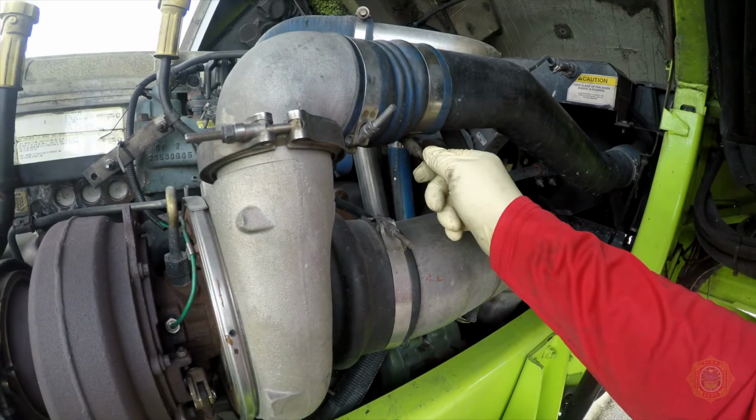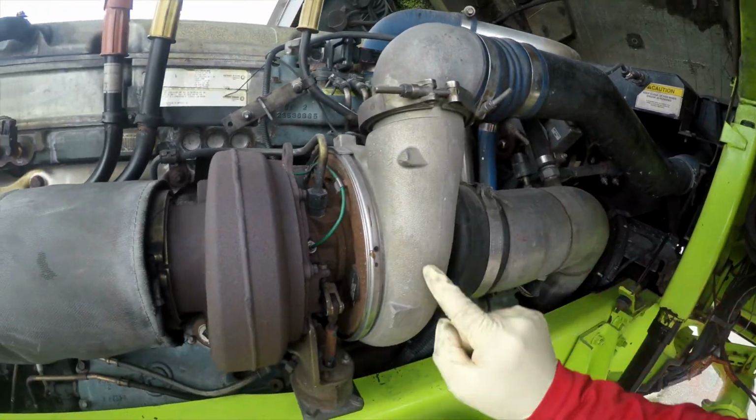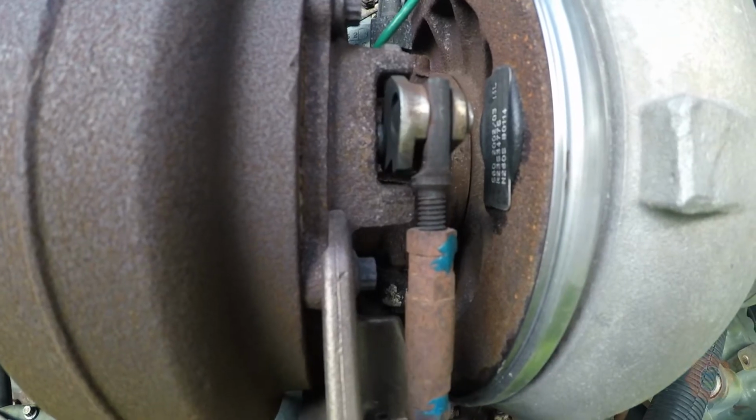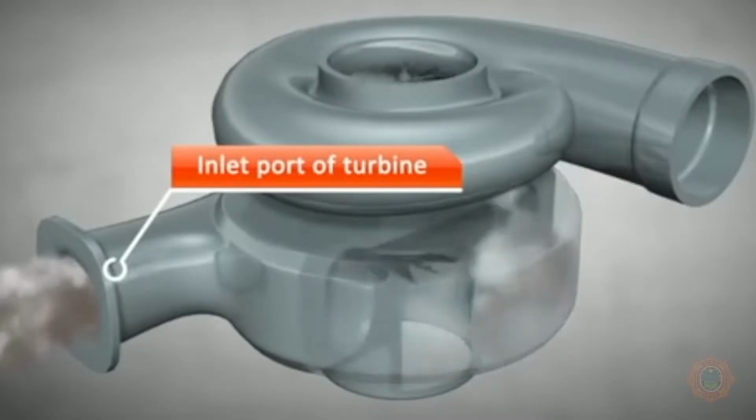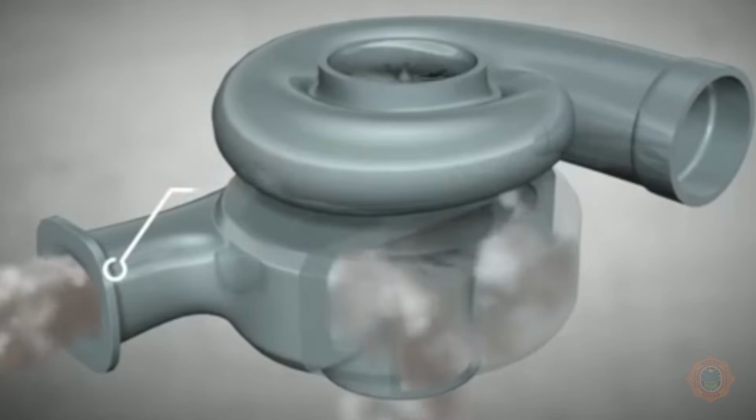Inspect the air intake to the turbocharger. The turbocharger uses exhaust gas to drive a turbine. This spins an air compressor that pushes extra air into the cylinders, allowing them to burn more fuel each second for better combustion of the fuel by increasing the intake air temperature.